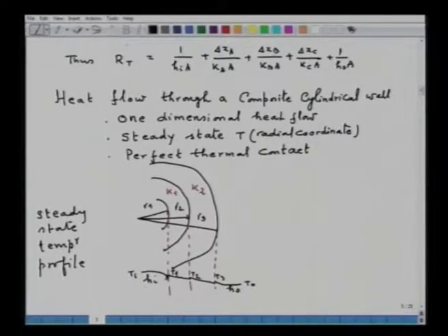So, we can also draw the thermal circuit, analogous to an electric circuit. All that we are assuming is that the walls of different thickness and different thermal conductivities offer resistance to heat flow, same as resistance offers to the flow of current. In the same way, the resistance offered by the brick hampers the heat flow through the wall.